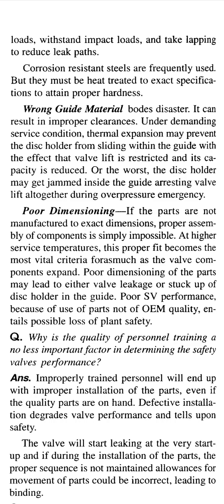Wrong guide material courts disaster. It can result in improper clearance. Under demanding service conditions, thermal expansion may prevent the disc holder from sliding within the guide, with the effect that valve lift is restricted and its capacity is reduced. Or, at worst, the disc holder may get jammed inside the guide, arresting valve lift altogether during an overpressure emergency.